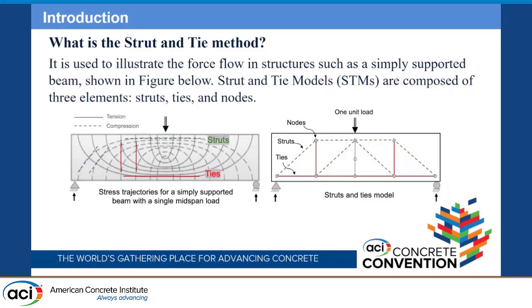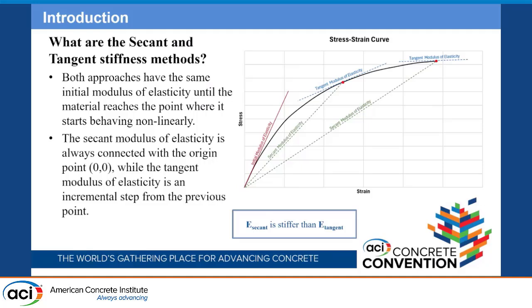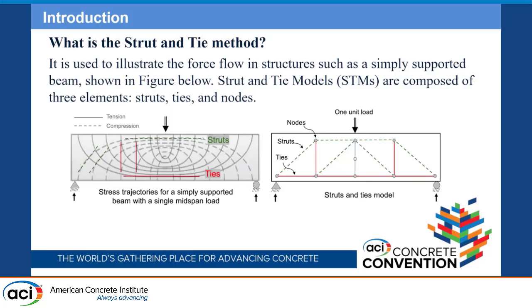This picture shows on the left-hand side the stress trajectories, which could be very well represented by a truss topology. And using the strut and tie model, we can handle that. Now, you might ask yourselves, why is he presenting that when this is something very important, very known to us, which is using trusses to analyze deep beams? The answer is the main contribution of this study is the fact that, because of these trajectories, the linear strain profile is no longer valid.